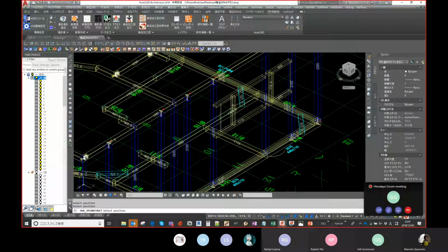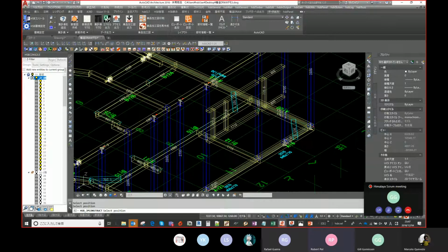And so, for example, here you see the Japanese construction. When you put a jack, there's no stud that goes down to the floor or to the top. It's just that position. Okay. And why is that? Because the top and the header and sill are carried by the posts. The structural forces are distributed to the posts.